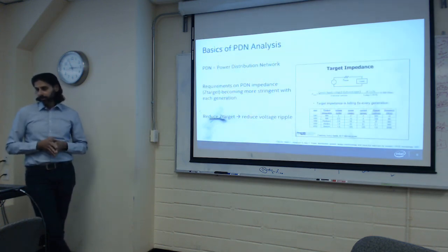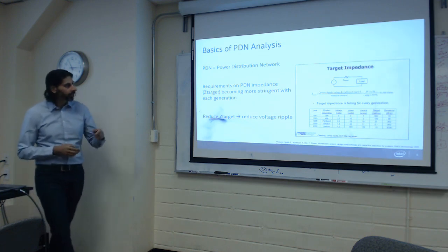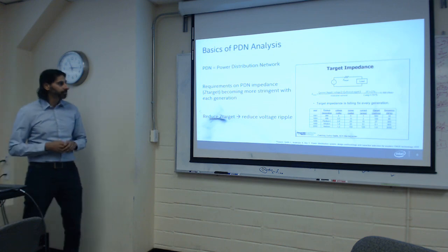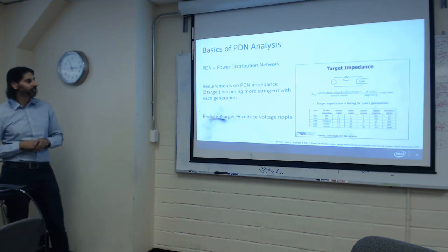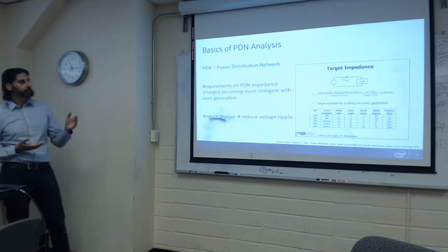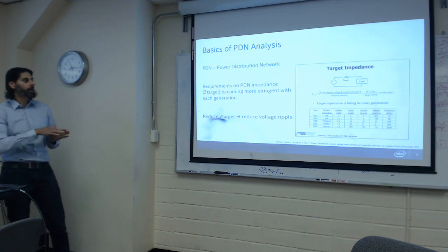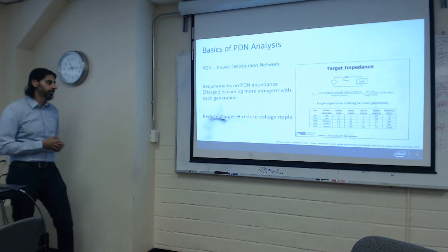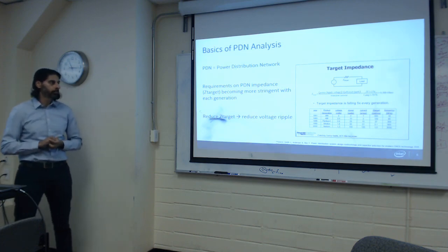So a little bit more about PDN analysis. As mentioned, it stands for Power Distribution Network. Some of the trends that are happening in the space, I don't know if you can read that chart there, but it's pretty old, from 1990 to 2000. But it's basically saying, as power consumption goes up, the voltage supplies, traditionally they were going down, but they've kind of stabilized now. So the power supply, you notice on modern FPGAs or even ASICs, are not shrinking or lowering as fast as they used to.